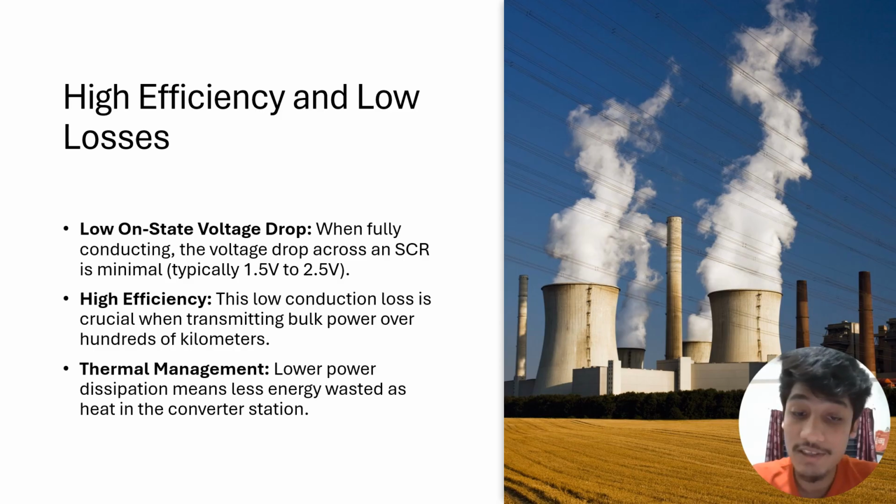Let's look at the first major advantage: high efficiency and low losses. When we are transmitting bulk power over hundreds of kilometers, every single watt matters. The primary benefit of an SCR in this scenario is its exceptionally low on-state voltage drop.